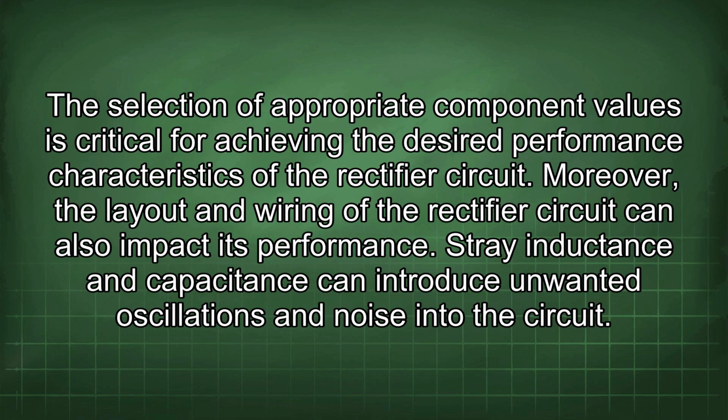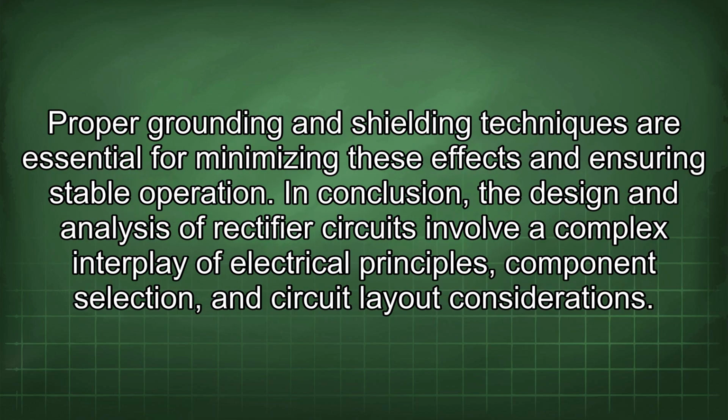Moreover, the layout and wiring of the rectifier circuit can also impact its performance. Stray inductance and capacitance can introduce unwanted oscillations and noise into the circuit. Proper grounding and shielding techniques are essential for minimizing these effects and ensuring stable operation.